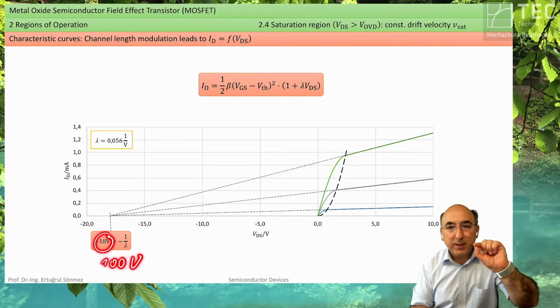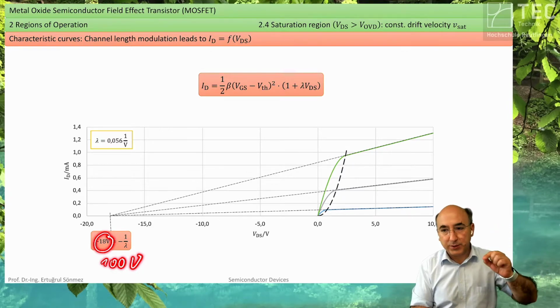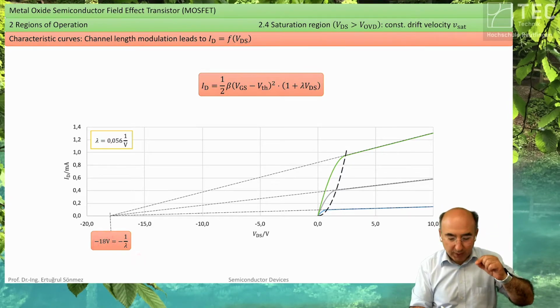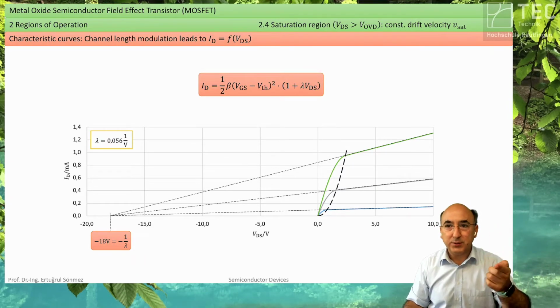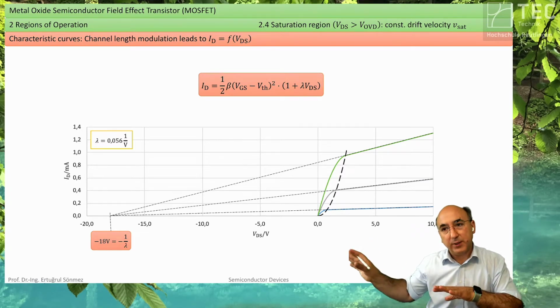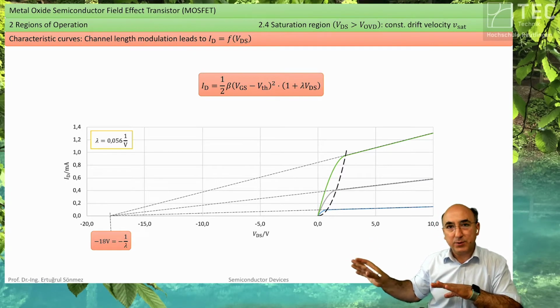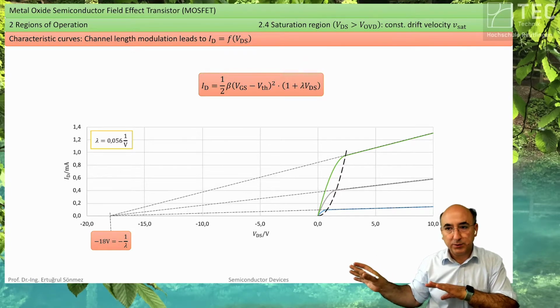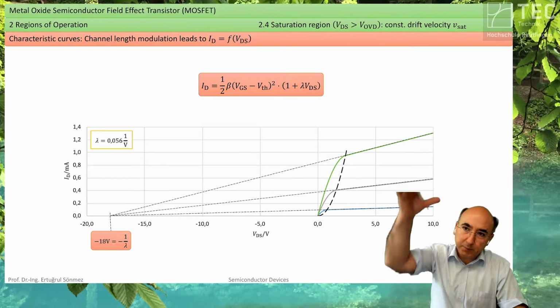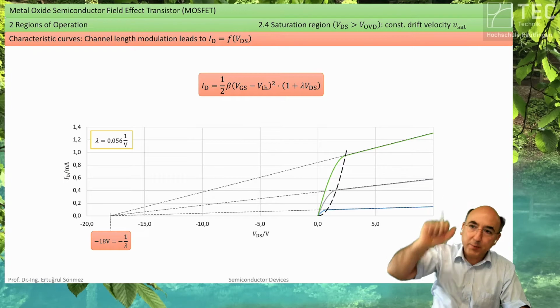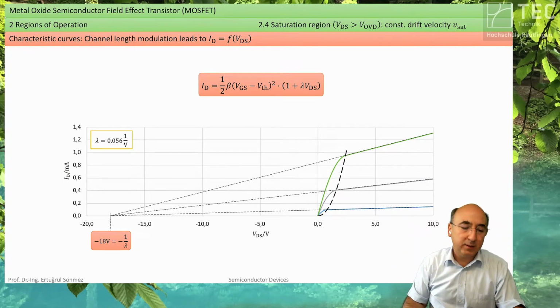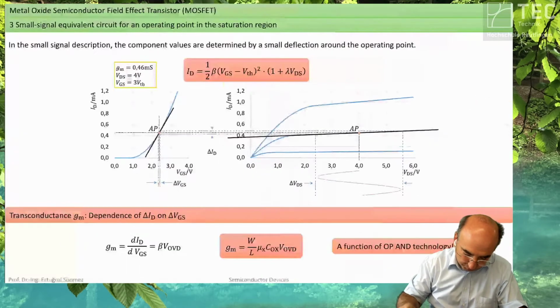That means, by nature, these bipolar transistors are better analog transistors. Therefore, in analog design, bipolars are favorite transistors. But as I said, the P-type bipolar is not really useful.